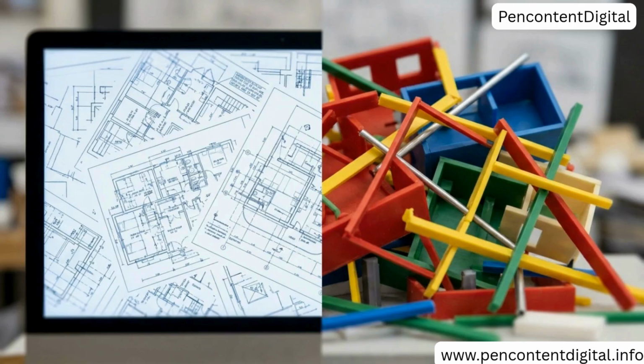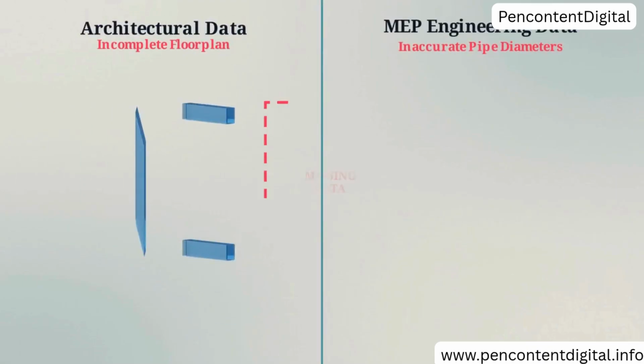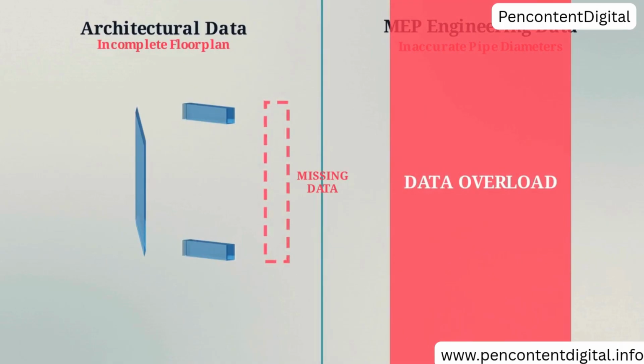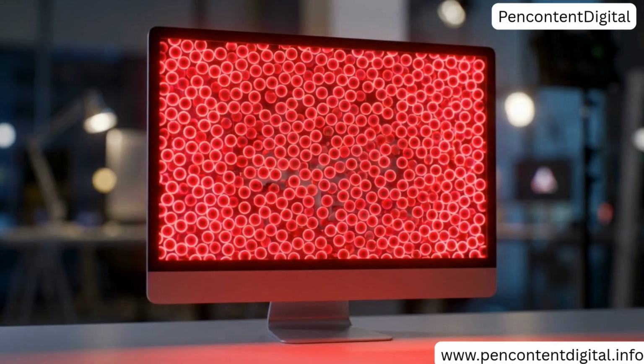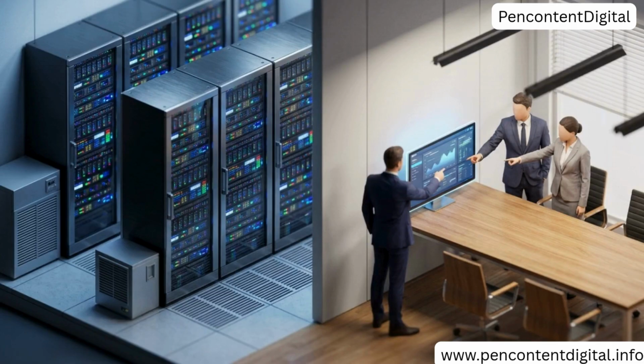But the ultimate constraint is the garbage-in, garbage-out data paradigm. Navisworks cannot magically fix bad engineering. If an architect imports an incomplete floor plan, or an engineer uploads inaccurate pipe diameters, the clash detective will yield false positives and fatal omissions. Its output relies entirely on the accuracy of the imported models. Maximizing the software requires high capital investment, paired with highly disciplined data hygiene across every department.